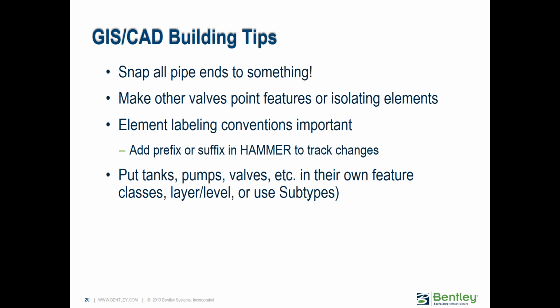Meaning if you have, for example, a spreadsheet and you have a worksheet in there, a tab that says nodes, and that includes tanks and pumps and valves all in one worksheet, that can make it difficult to import into Hammer, because you're mapping a table, and in the case of a spreadsheet, it's a tab, a worksheet in your spreadsheet. You're mapping that to a specific element type.